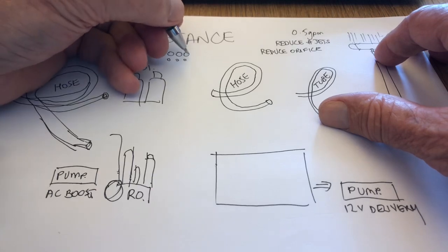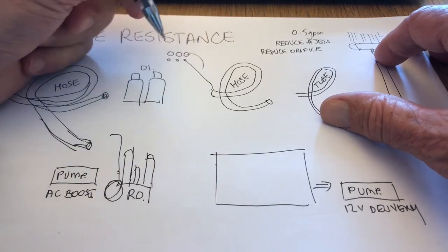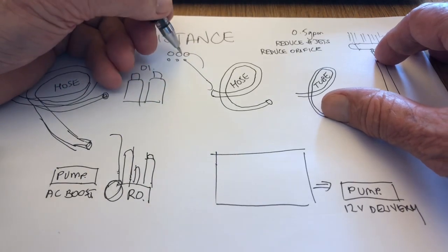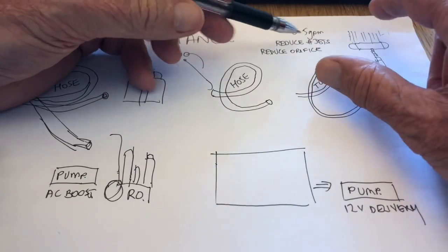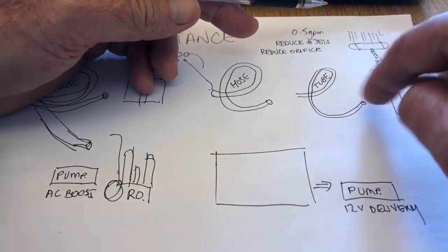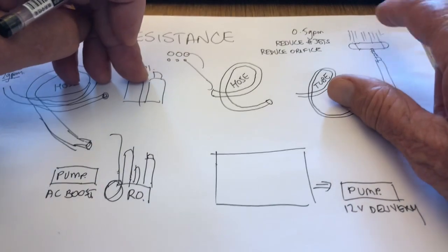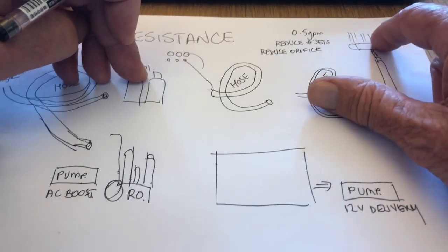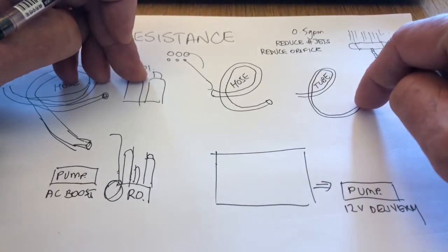In this sense, the water will go like this, and in this sense, the water will go like this and then drop with gravity. So by reducing the orifice of the jets, we can increase the velocity through the brush, and depending on how the rest of the water delivery system is set up, it won't change the flow rate, whatever flow rate you've got there. If you don't have enough flow rate there, then you have to change the resistance elsewhere.